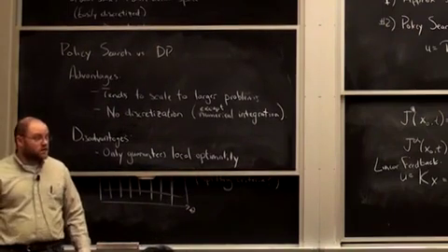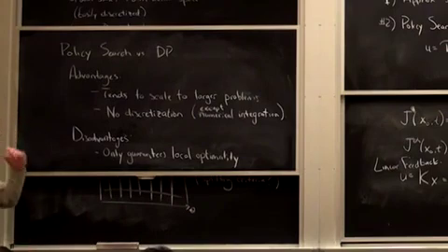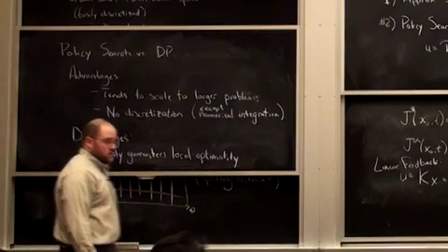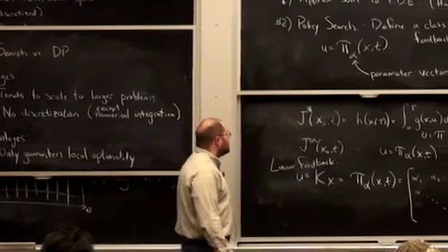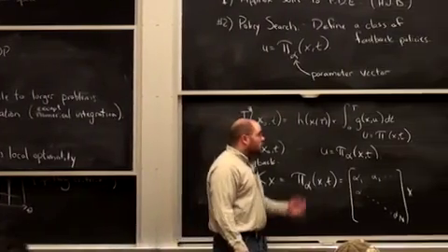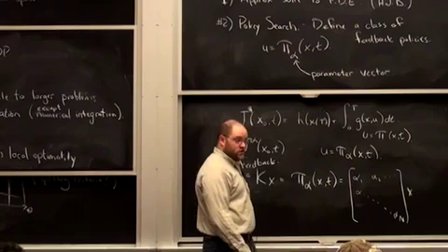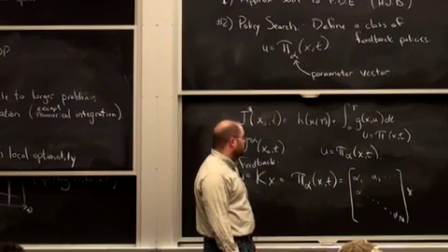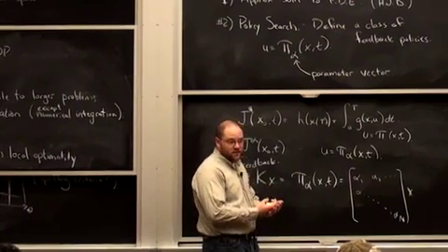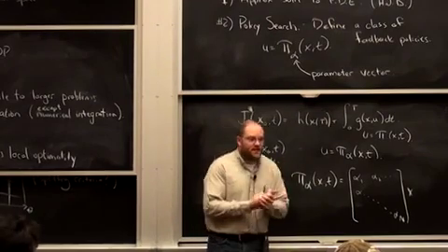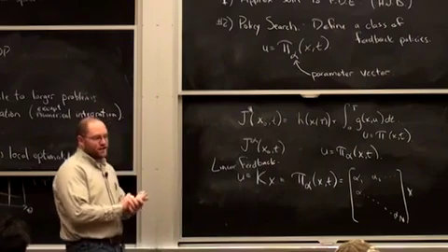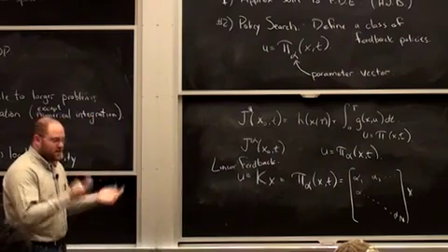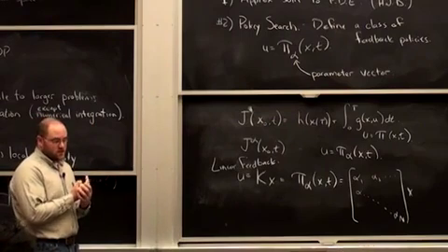Yeah, please. When you use function approximation, isn't it like discretization of your state space? Not necessarily. It's a good question. So take the linear feedback example, right? If I take an LQR problem and I solve it with policy search, and I know the feedback policy should exist in the class of linear things, then I haven't lost anything by doing an approximation.